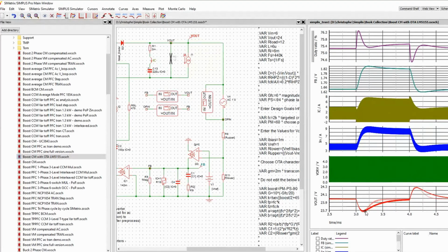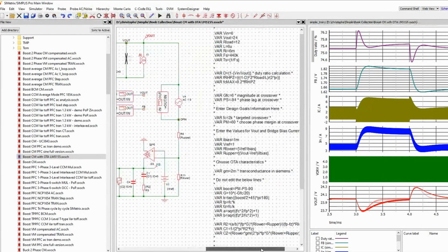However, the recovery time here depends on the phase margin. So the more phase margin you have, approaching 90 degrees, the more sluggish the response you're going to have, but the less overshoot you're going to exhibit. And if you reduce the phase margin, you recover at a faster rate. However, you will probably start to have a little bit of overshoot here. The converter becomes more nervous.